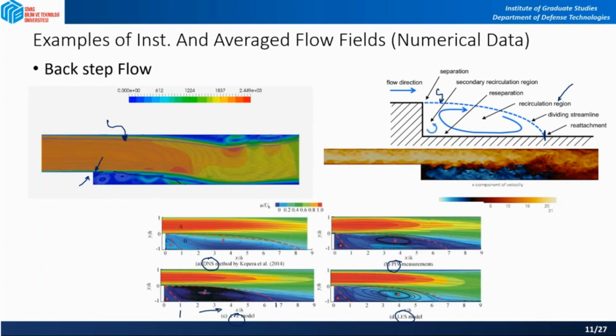So the problem is when you directly solve for RANS, like using K epsilon in this part, and you hope that you can capture this reattachment distance, this distance that I showed you. When you do the DNS or LES, or when you do this experimentally, you will get the distance correctly. But in numerical solutions, you might not get that distance correct.